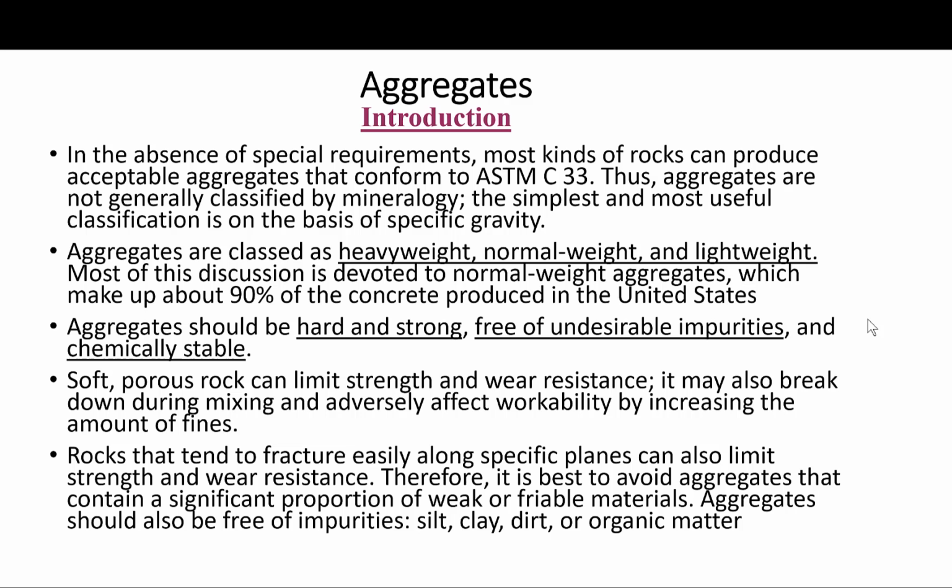All right. If these materials are not removed, and they coat the surfaces of the aggregate, they will isolate the aggregate particles from the surrounding concrete, causing a reduction in strength. For example, silt, clay, and other fine materials will also increase the water requirements of the concrete, and some organic matter may interfere with the cement hydration. So there are standard tests used in the United States to evaluate aggregates, as might be discussed later.